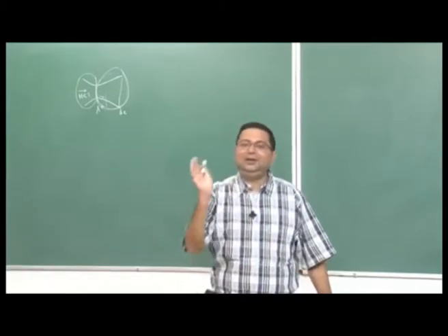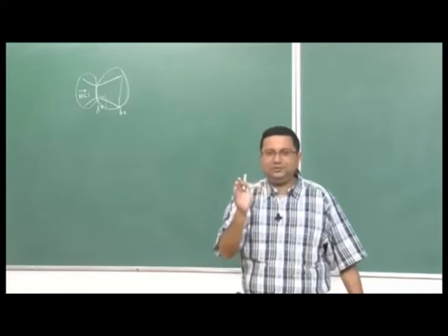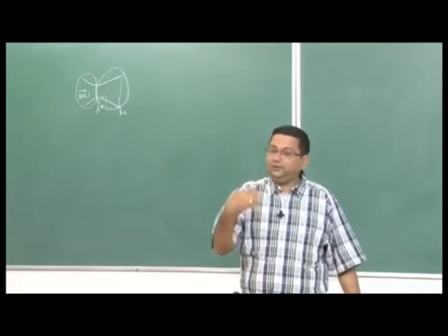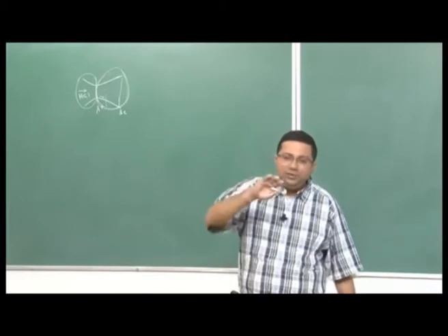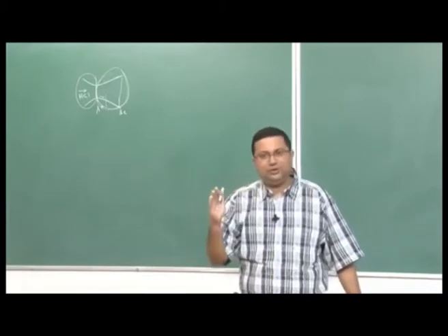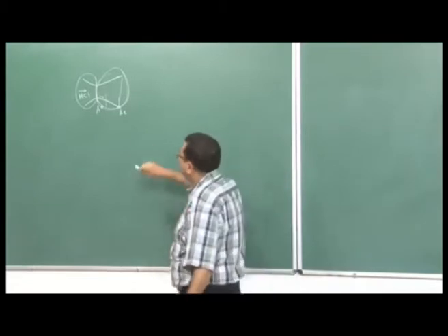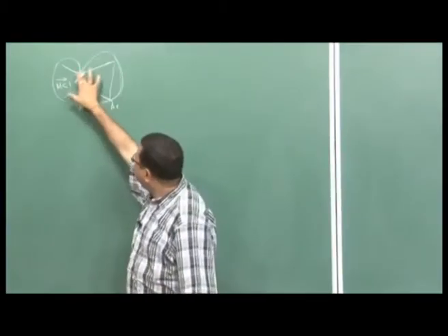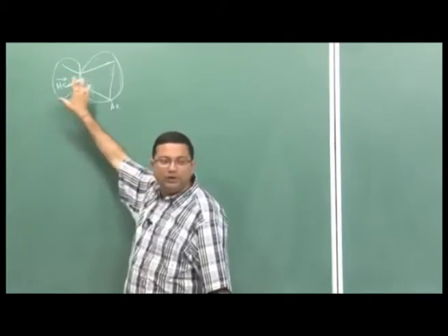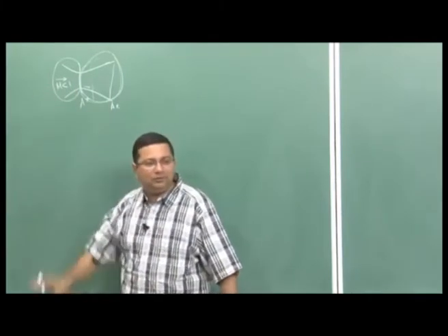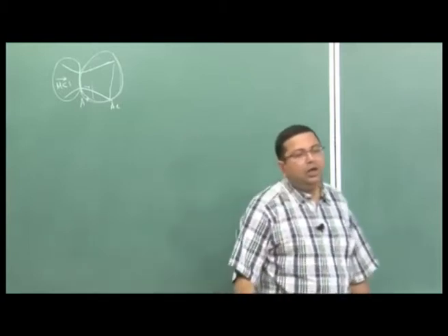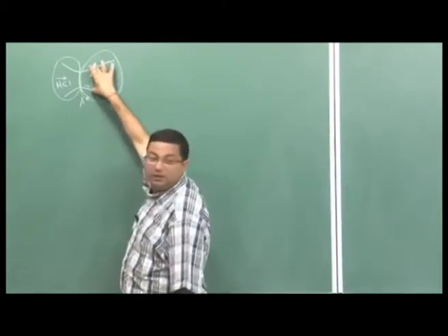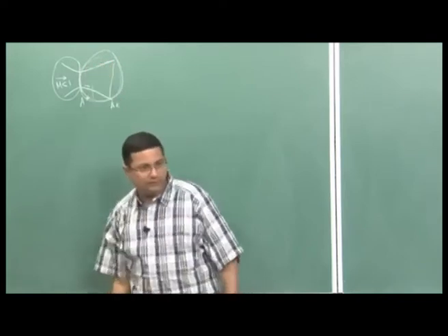But the strength of this expansion fan, or whether we are going to have an expansion fan or not, and whether it is going to be isentropic or not, depends on the design, on how much curvature we provide. We cannot choose arbitrary curvature; it has to be specific curvature. Therefore, the design of this portion is more important than the design of this portion. So, in the next couple of lectures we will be focusing on the diverging portion of the nozzle.